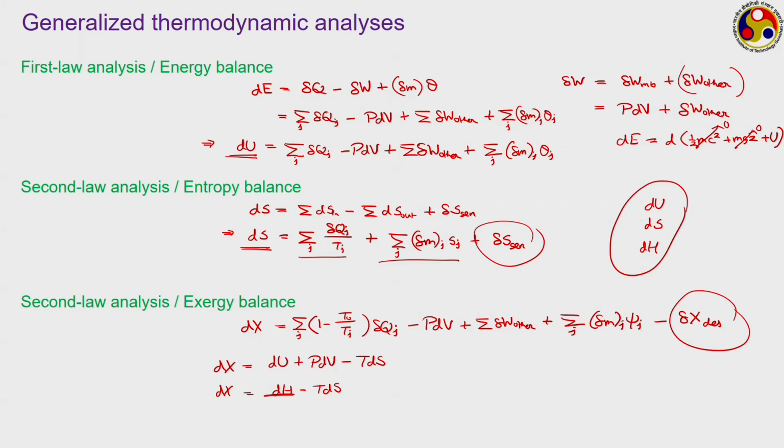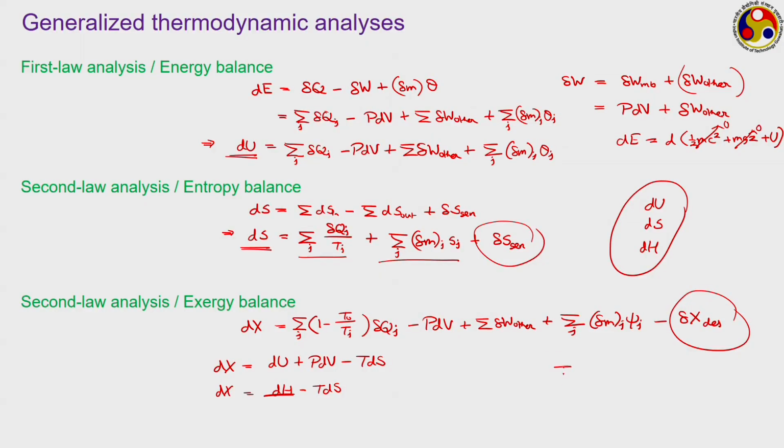In thermodynamics we can classify properties in two different manners. Of course, one type of classification is intensive and extensive, but here we are talking about the practical sense. A group of parameters like temperature, pressure, specific volume, mass, etc. can be measured very easily, whereas parameters like internal energy, enthalpy, entropy, etc. can't be measured directly.